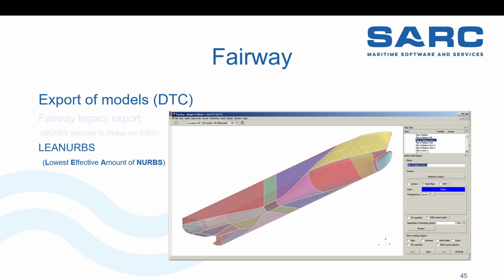Regarding the importation from an IGS model, what happens if you import a surface that was originally trimmed? I think that's okay now, because we only import the curves in that model. So we can import a trimmed surface model. Good question, by the way. We don't export them, but we can import them, because we will deconstruct the actual curves in that model. But I will show you why it will not work in the next few slides.